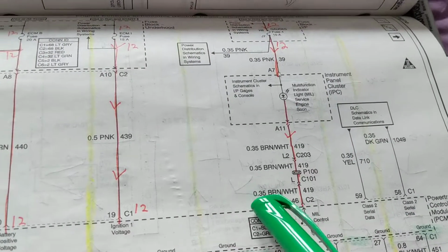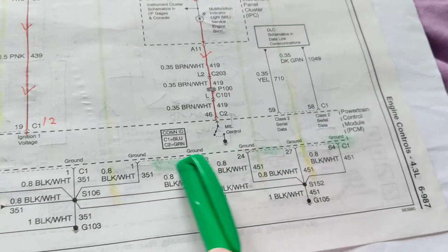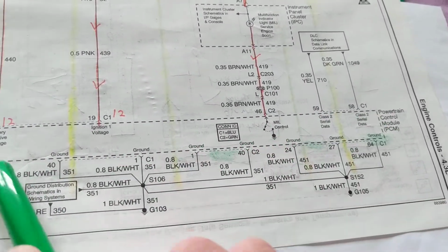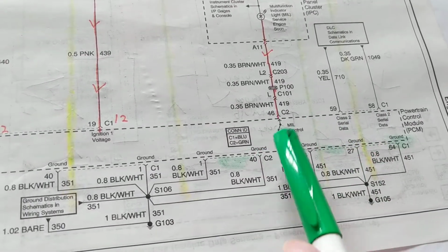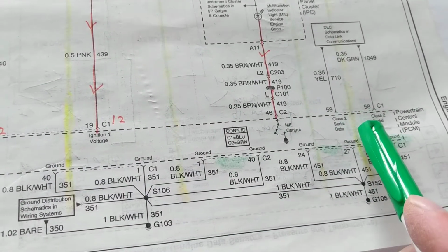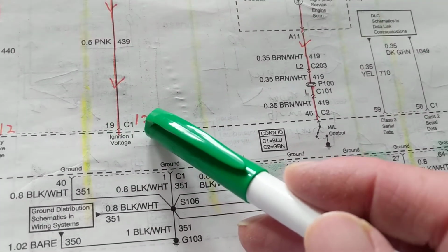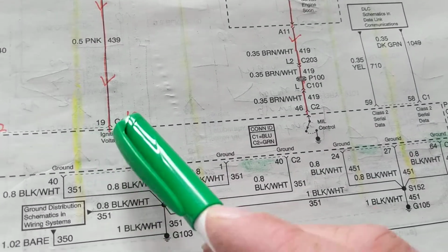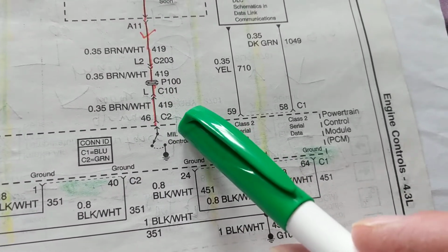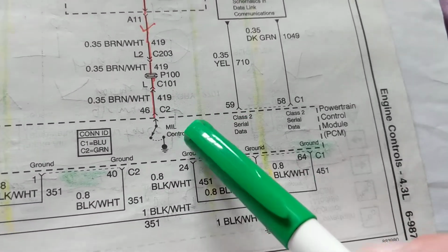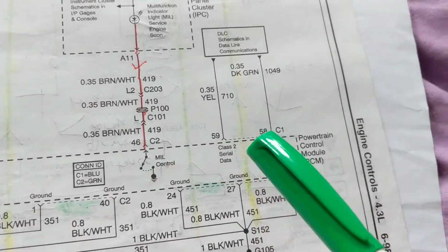For example, the power control module, which is a main computer module. Its first task is we have to give it 12 volts. If you look at this, see the dotted line around this? That means there's another part of this computer module. And believe me, there's about 200 pins on this computer module. As you can see over here, there are connectors. See these little triangles? These are connectors. These are the pin numbers. Pin 19 is the pin number for ignition voltage, 1. Pin 46 for connector C2 controls, as you'll see over here, the malfunction indication light.